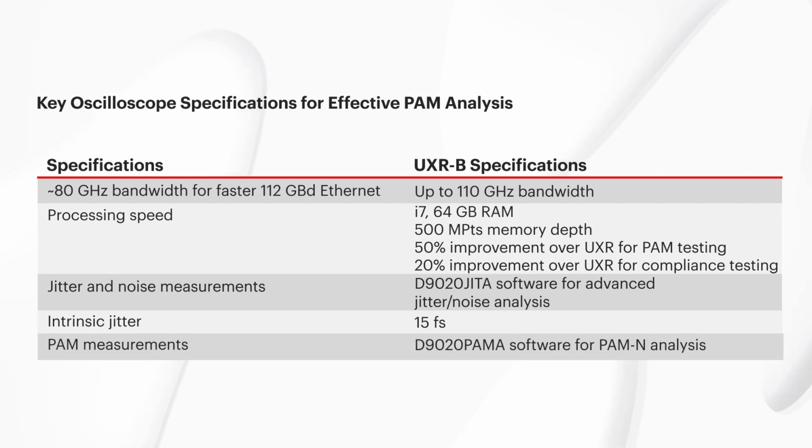Because especially as we're dealing with closed eyes, and whether or not we're applying equalization, we're looking at the end of a very lossy channel. So there's just not much signal left. So not only having enough bandwidth, but having a low enough noise to be able to make those measurements. Last but not least, even with the best-in-class oscilloscopes, these measurements are a challenge.